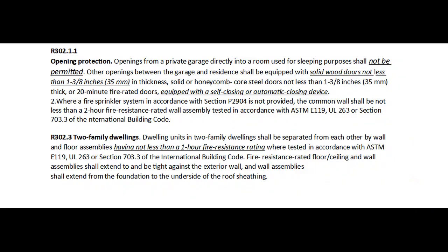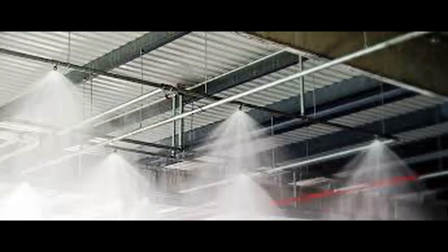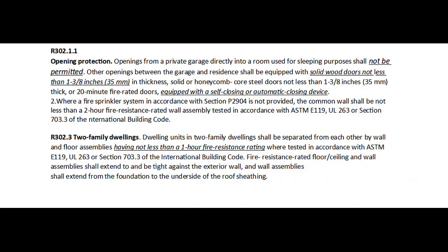2. Where fire sprinkler systems in accordance with section P2904 are not provided, the common wall shall not be less than a 2-hour fire resistance rated wall assembly tested in accordance with ASTM E119, UL 263, or section 703.3 of the International Building Code.